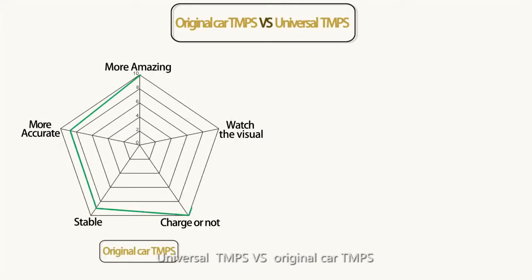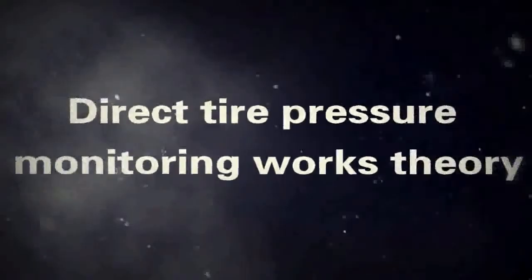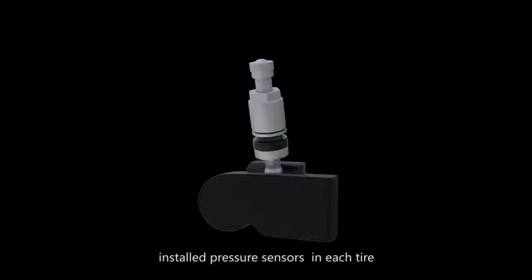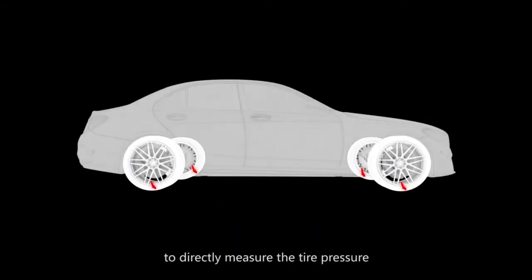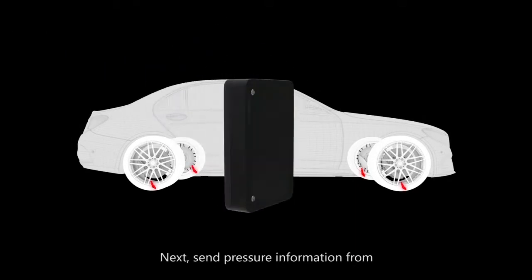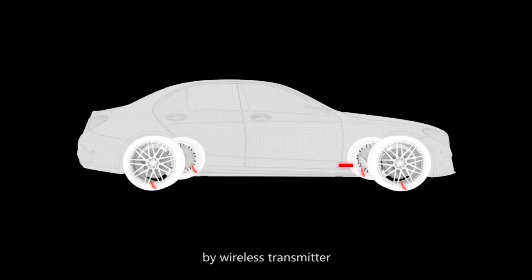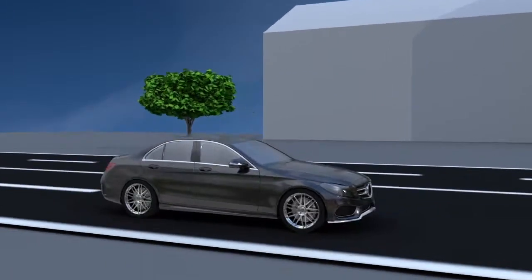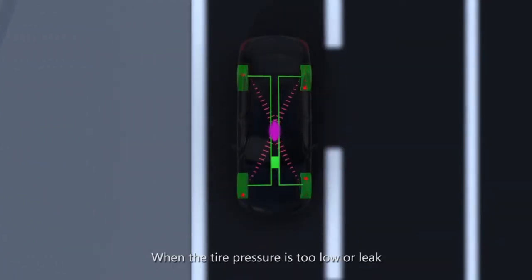Original car TPMS versus universal TPMS. Direct tire pressure monitoring works in this way: pressure sensors are installed in each tire to directly measure the tire pressure. Next, the pressure information is sent from the tire to the central receiver module by wireless transmitter, and then the tire pressure data is displayed. The system would automatically alarm when the tire pressure is too low or there is a leak.